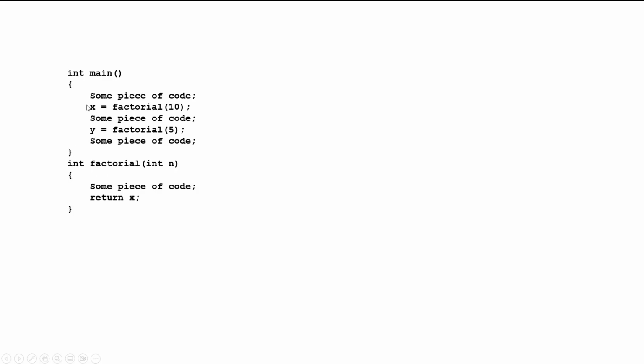So now we can come back to that after the function returns. If we call from here, PC+1 will be saved in the register. So when we jump based on register, we come back here. If we call from here, then this PC+1 will be saved, and when we return, we can come back here. So by adding JAL, jump and link, and jump based on register, we can actually have function call and return support as well.